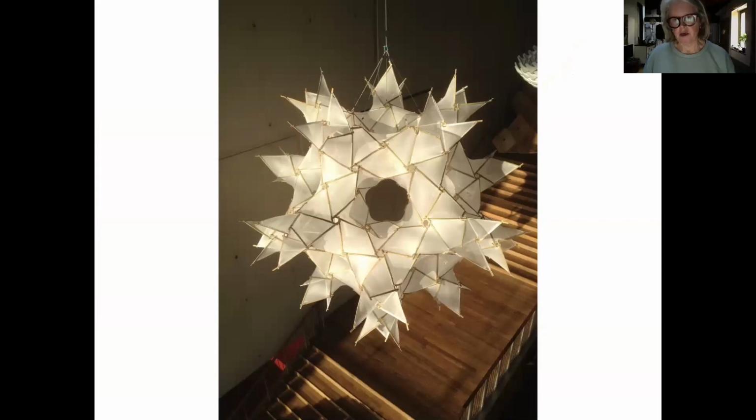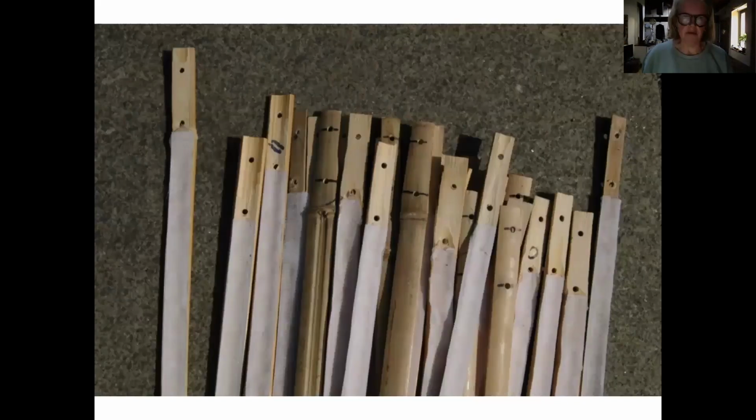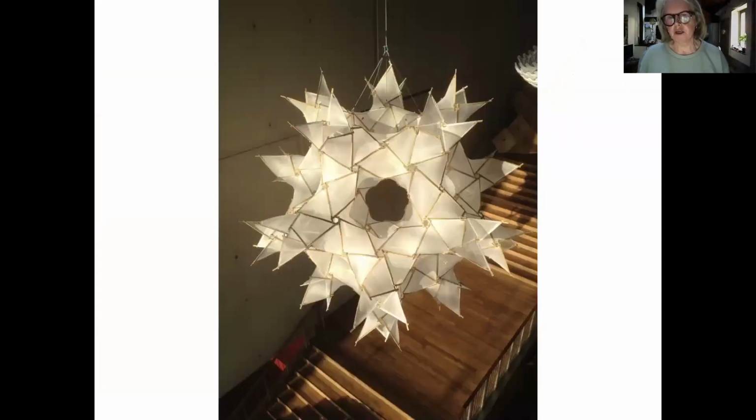And that was the competition entry at Amsterdam, the IASS Spatial Structures Pavilion competition in 2015. So with pieces of bamboo that were about 55 centimeters long, the overall structure was 4 meters in diameter. And by putting Velcro on the bamboo, it's very simple. As I say, I prefer the primitive approach, but sticking Velcro on the bamboo and then putting Velcro on the lycra patches means that you can make a cladding for the shapes, which defines the form a little bit better. And the stretchiness of the fabric also gives you good definition of the hyperbolic curves, the saddle shapes.